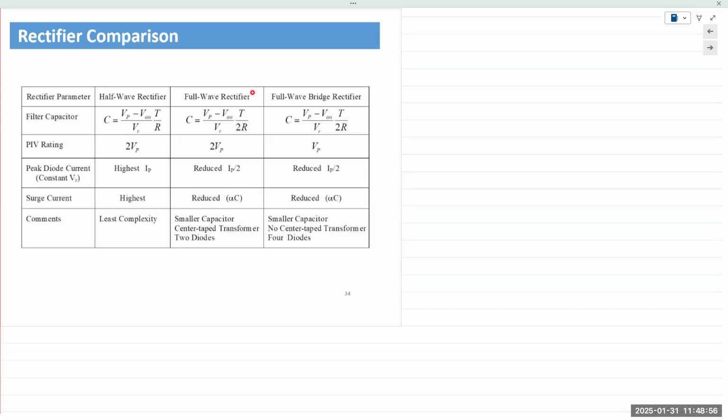You're rectifying 120 volts, converting it into DC or pseudo DC, and then inverting it to get an AC output again. So you take the DC, step it down, and convert it into high frequency AC, and with high frequency AC you can use a very small transformer for the same resulting voltage. But again, that's a separate discussion.